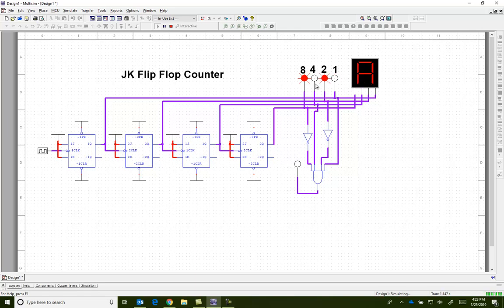We're going to keep scaffolding until we get a counter that has other limits other than 8 and 15. So instead of just turning on this little green light when it reaches 5, what I would like you to consider is the following. Not only turn on this little green light, but also the moment it counts to 5, immediately come back and start back at 0. So force all of these flip-flops to 0. So take a moment to think about it. What do I need to do to any of these flip-flops to override, to force a 0? If your answer was activate the clear, you're correct.